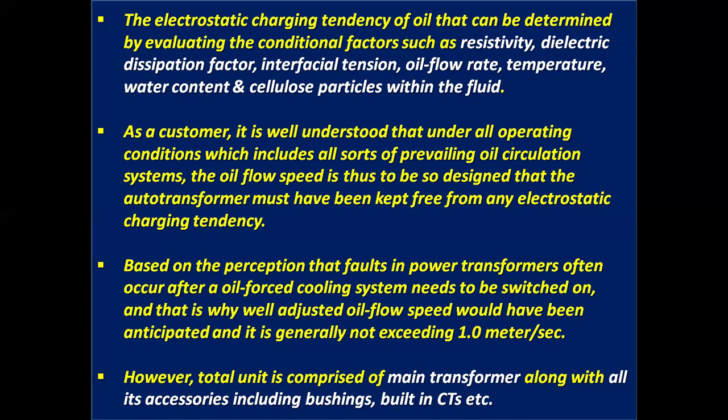Based on the perception that faults in power transformers often occur after an oil forced cooling system needs to be switched on, a well adjusted oil flow speed is anticipated, and it generally does not exceed 1 meter per second.